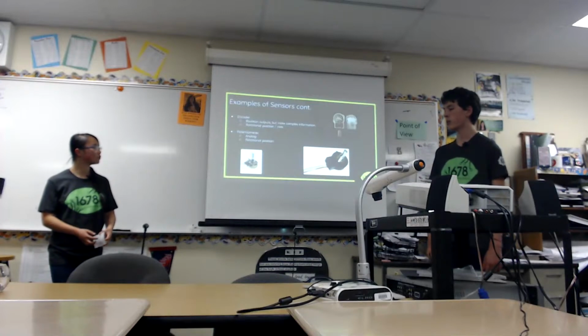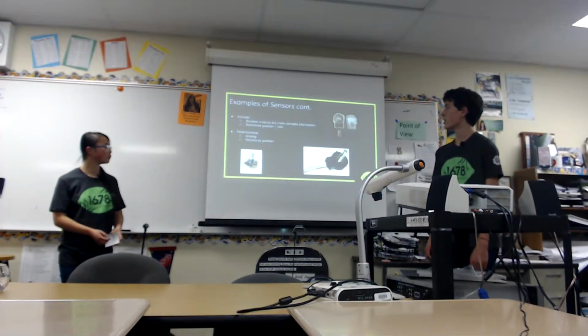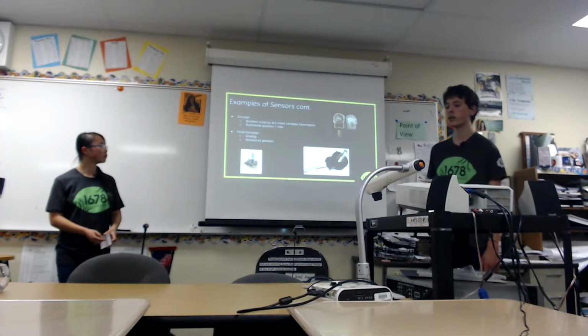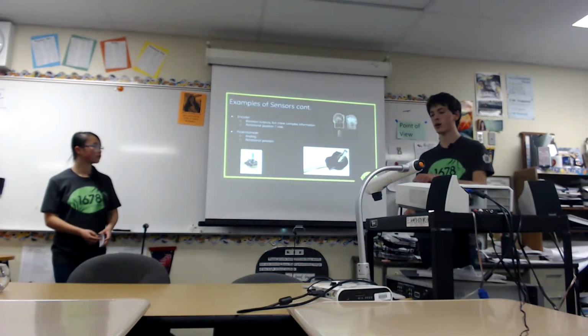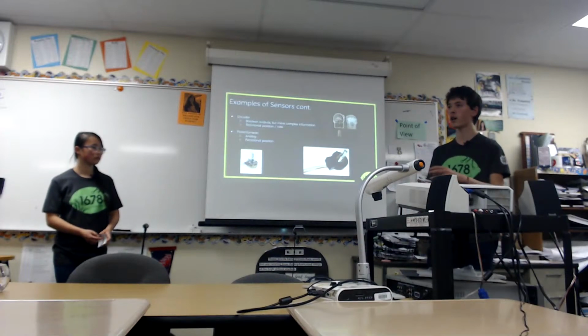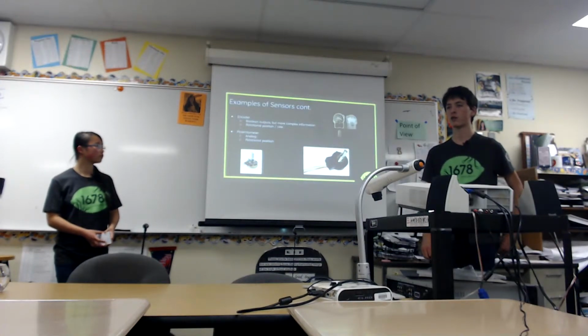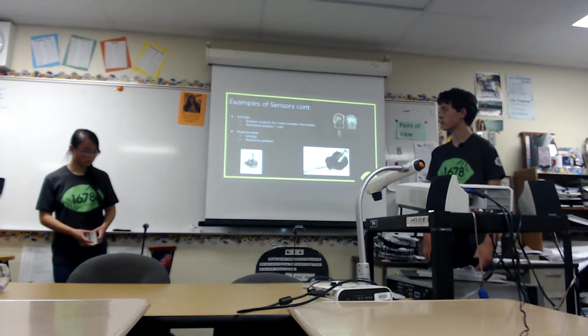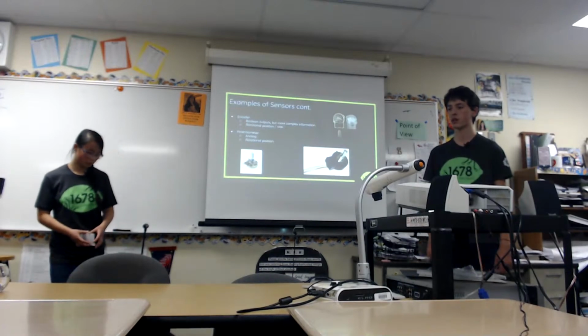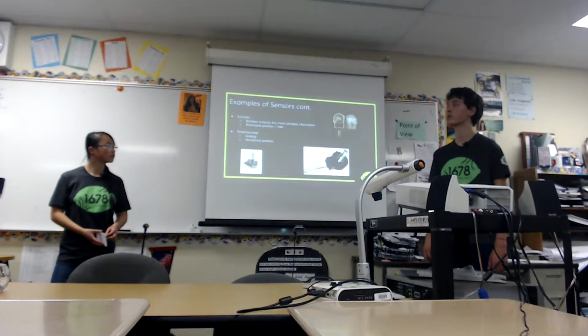They do the same thing, but the good thing about a magnetic encoder is that you don't need a physical connection, because with a physical encoder, you have to attach the shaft of the encoder to another shaft on your drivetrain, and that's just another part that could fail. But with magnets, your magnet's not going to come sliding out if you super glue it in place.